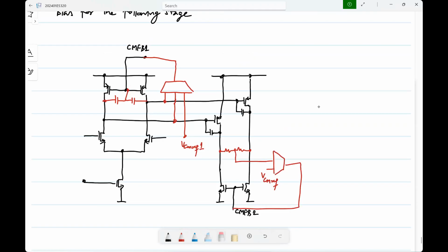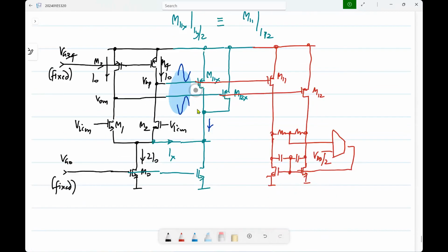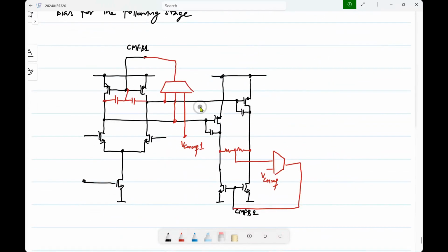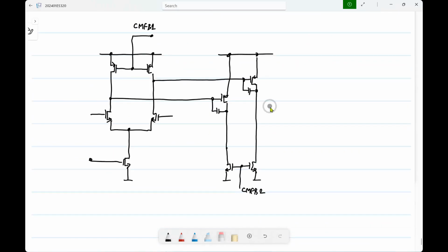Okay. So the bottom line is, in fact, I showed the other circuit also, which is more efficient, something like this, where you inject a current here to the tail to stabilize the common mode. But the common feature to all these is that you have a separate common mode feedback for each stage. The first stage output is stabilized and the second stage output is stabilized separately. Okay. Now this is actually a good choice. Typically, this is well behaved and so on. But sometimes there may be need for a slightly more economical circuit or something like that.